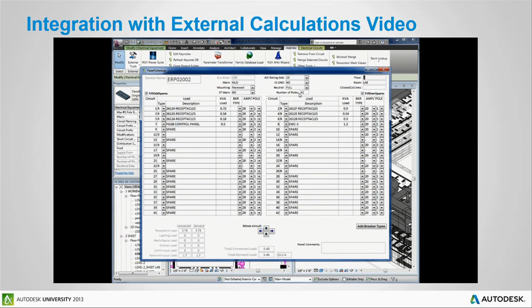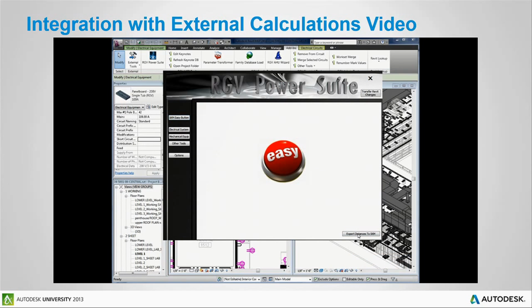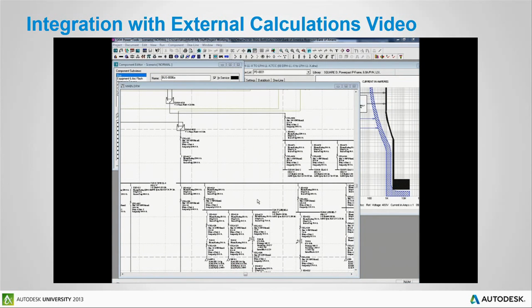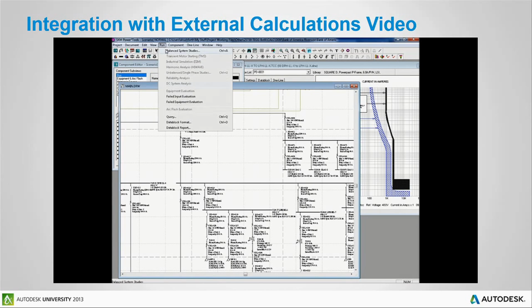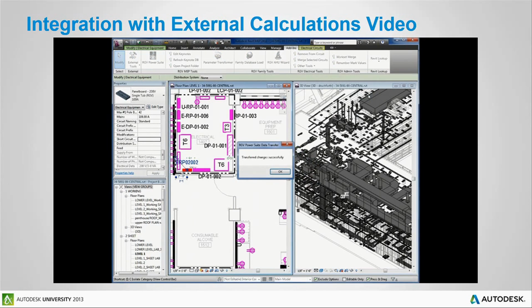Short circuit and voltage drop calculations can be automatically computed in the database, or you can choose to export Revit system distances to SKM Power Tools for more advanced system modeling and analysis. Once complete, the results of the SKM analysis can be pulled back into the database. The combined updated data, including accurate equipment ratings, can then be sent back into the Revit model for all the equipment.